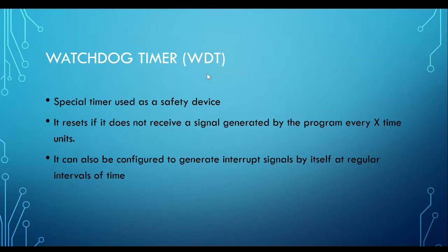Watchdog timer, like what I explained, helps you to reset the device. If your device has hung for some time, it will help you to go into the reset address. We discussed the computer cycles: fetch, decode, and execute. It continuously does this, but sometimes it hangs.